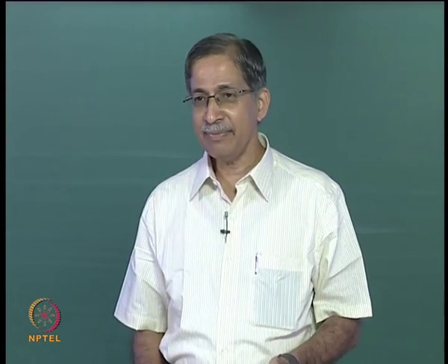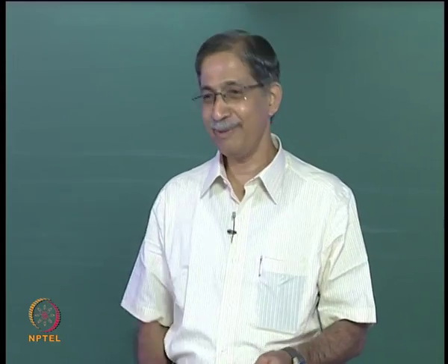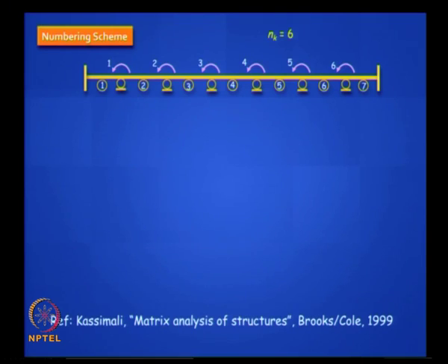How will you number them? Well, it's straightforward here. You number them sequentially like this. Remember, anti-clockwise positive. Earlier we did clockwise positive, but now we are doing anti-clockwise. 1, 2, 3. This is fairly obvious. Supposing I do it in a funny way. I put 1 here, then I choose to put 2 here, then I put 3 here. What do you think will happen to the stiffness matrix? It's a good question. It will just shift the columns.